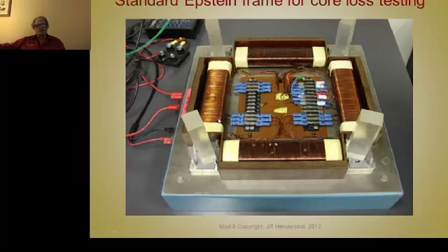So you weigh the samples, build this frame out of them, weight down the corners so they're in contact, and then you apply a variable voltage and variable current and frequency to the primary, and by measuring the voltage generated on the secondary, you determine the losses in watts per pound or watts per kilogram of the material, and that's how they make the measurements that they publish.